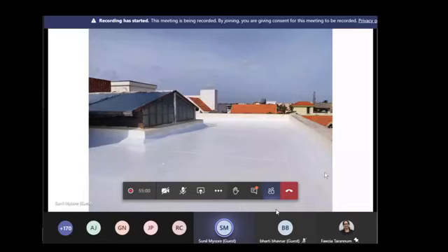So this is about the catchment. Most important, keep it clean. Catchment clean is water clean. Most of the other things are actually a myth. If you keep the roof clean, there is nothing more that you need to do, because the only source of contamination for rainwater is your catchment, that is your roof. If you keep the roof clean, the rest of the things just fall in place by themselves. It starts from here. If you can keep the catchment clean, you can maintain the rest of the system. If you can't, it's quite obvious that you can't maintain the other parts of the system.